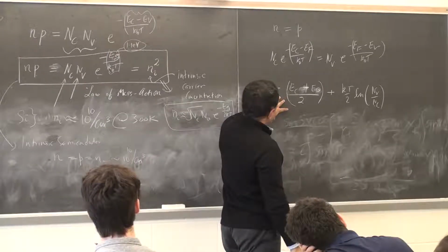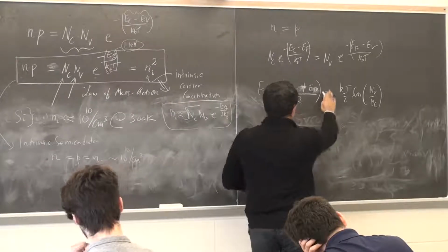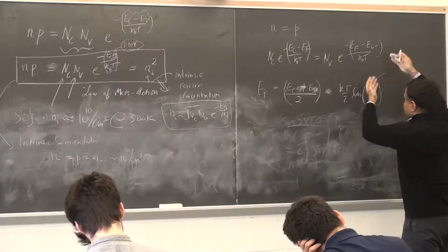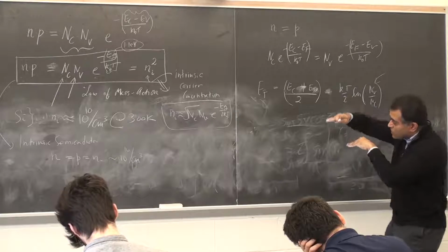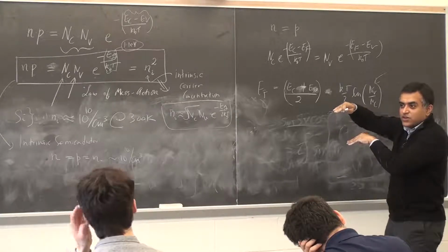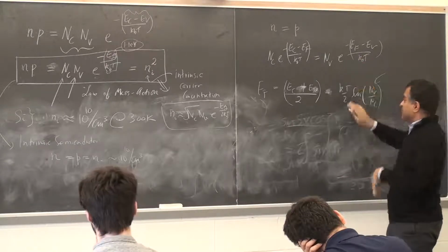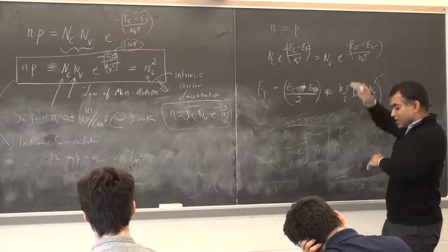Okay. Did I say that right? Maybe it's minus then. So I just want to make sure. If my valence band density of states increases, then the Fermi level should go away from the valence band. It should get away from it to have the same amount of carriers. So actually, I was correct. It should go up.